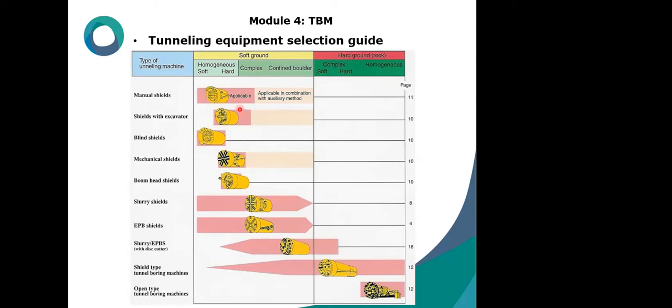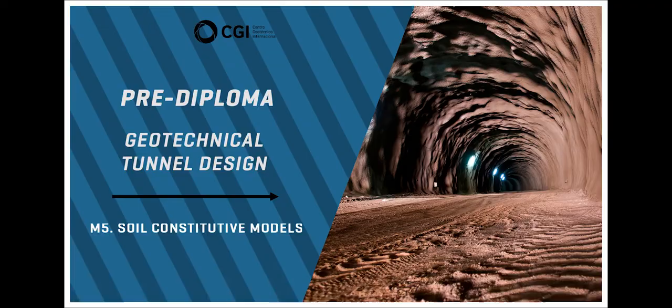It should be indicated that the supporting systems in TBM differ from what is in NATM. We don't have initial and final lining. We have segmental lining as both initial and final lining. The mobilized forces, therefore, depend on the construction method that we will talk about later.